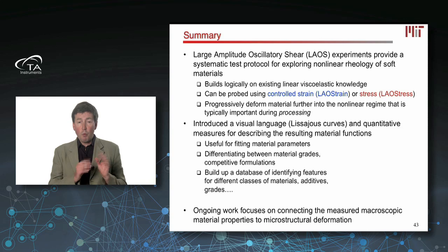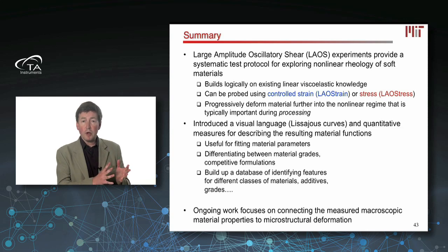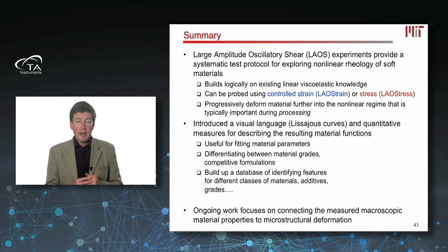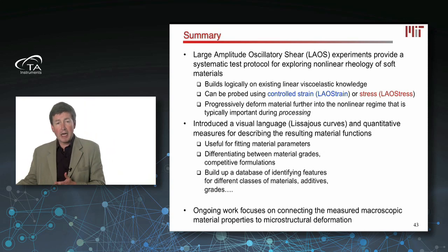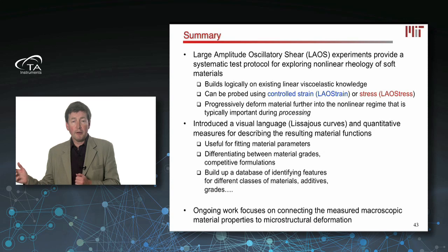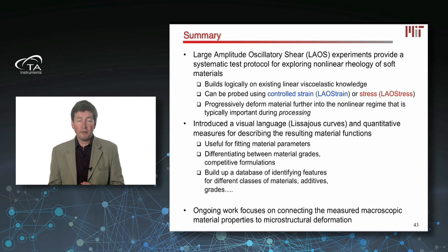Just bear in mind that in one you measure modulus, and in the other one you measure compliance. And what you're really doing is running into the nonlinear regime. You're running over the edge of that cliff and deforming the material in a way that's probably very important if you're interested in, for example, processing of your material. So linear viscoelasticity is great for small strains. When you fill a bottle or you fill a mold, you're typically in the nonlinear region of the curve.